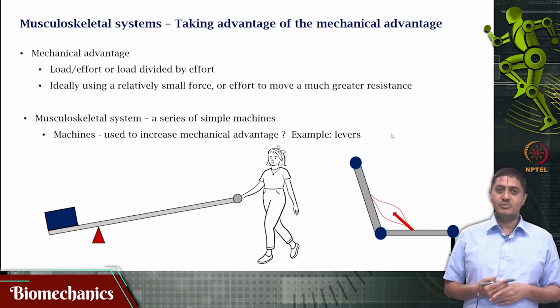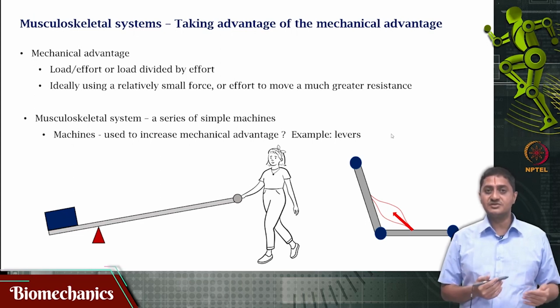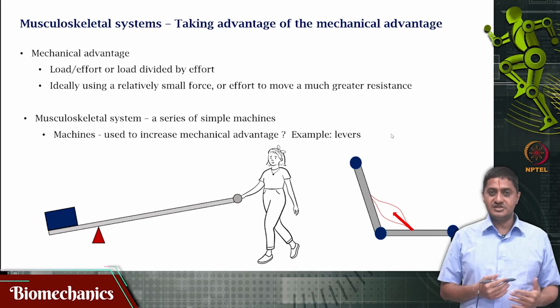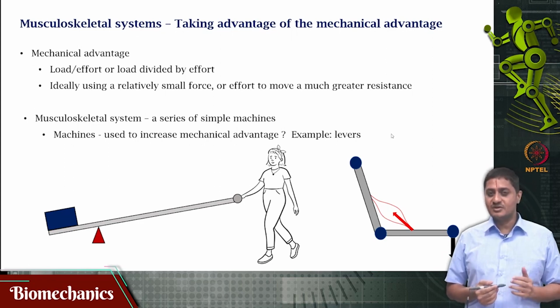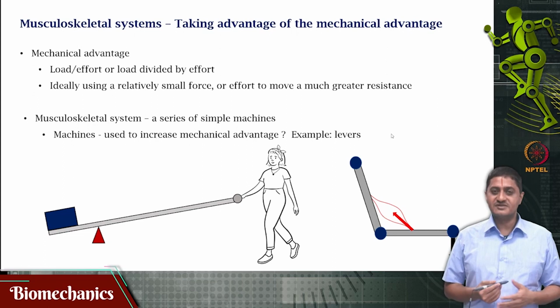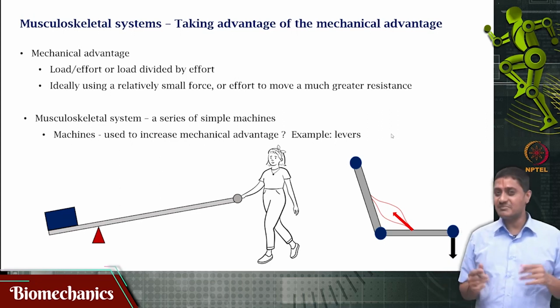And because the moment arm is the greatest when it is closest to the opening edge, that is where you keep the handle, because the force that will need to be produced will be smaller. So the effort that a person will have to put in to open or close the door can be minimized, for the same system.